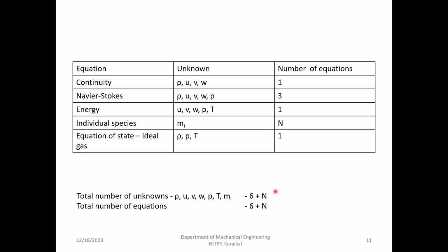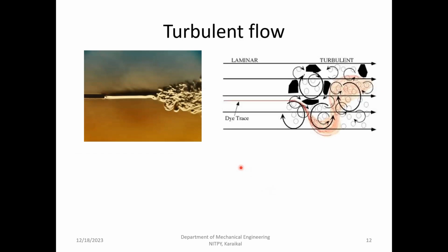We change it to ideal gas. The reason is, density is going to vary from point to point, and that must be calculated. We cannot take a constant density and then solve for a supersonic flow. If you do that, the number of equations and unknowns will not match, and the results will not be correct. Okay, so that's about the material properties.